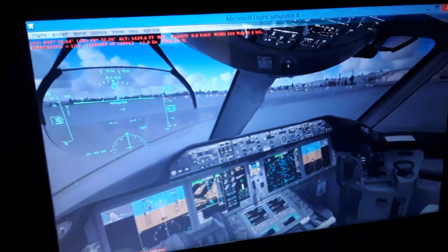Also, it can calculate the velocity difference between our aircraft and the other aircraft, so the velocity closing in. So if we have an incoming collision, it will give us, using the TCAS system, the traffic collision avoidance system, will display the other aircraft advisory. We have to make an evasive maneuver in the air.